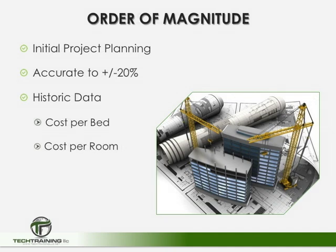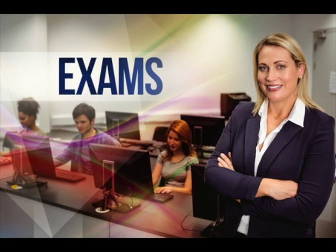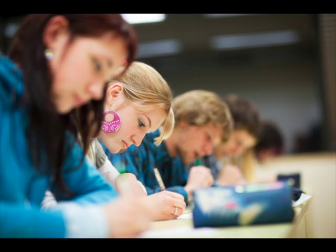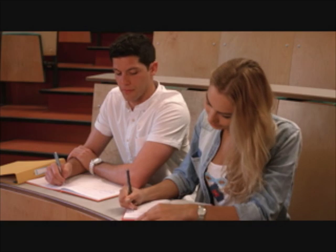Now again, this type of estimate is typically done in the initial project planning stage, and if you have decent historical data, you can take that accuracy from plus or minus 25% down to maybe plus or minus 20%. But again, in order to do that, we need to have historic data. And in many cases, this is based on the cost per bed or the cost per room or some other variation depending upon the project type. As an example, if it's a school and the school costs $1 million and there's 10 classrooms in the school, you would say each classroom costs $100,000. And then you could apply that to a school that's going to have 20 classrooms, and you'd say, okay, 20 classrooms is going to be $2 million, and so on.